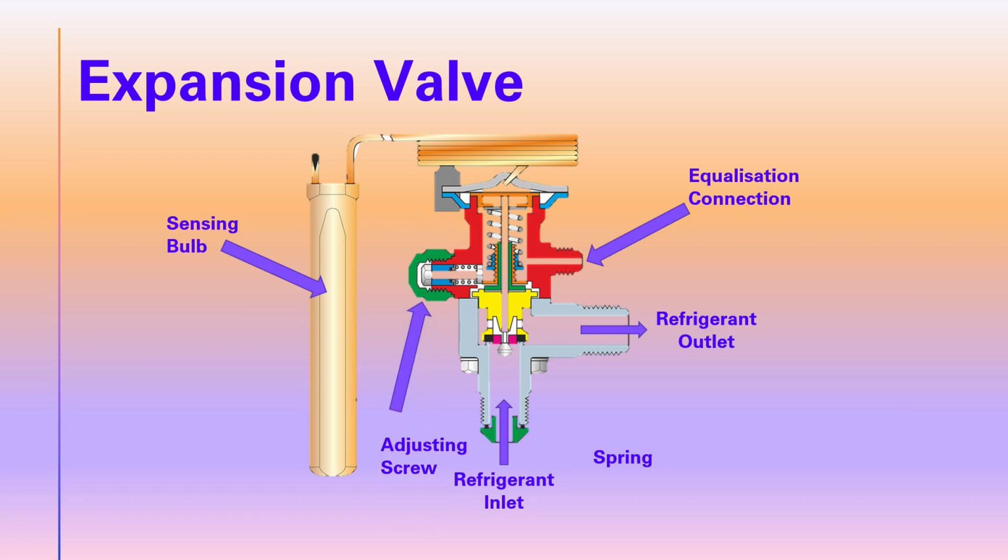Next is the adjusting screw, where you can increase or decrease the superheat setting. And we have the all-important spring, which pushes up against the diaphragm and closes the valve.